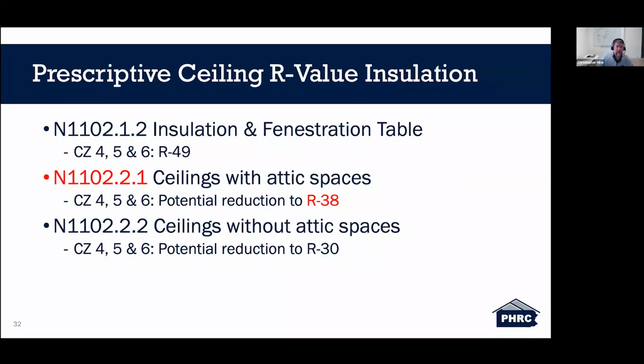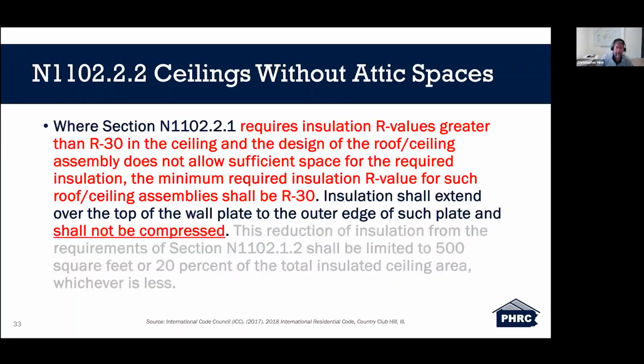So again, here we are, N1102.2.1: ceilings without attic spaces can be reduced to R38, and here's exactly what I just worked through. That reduction can now be reduced to R30, as long as the roof ceiling assembly does not allow for anything greater.